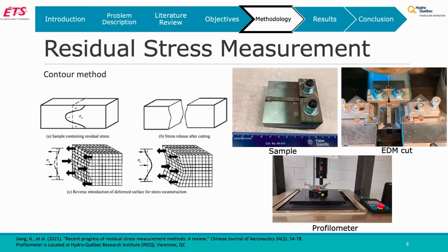And here you can see the sample, the CT sample mounted on the bolt head, and this is the EDM cut. So the EDM cut goes through the crack plane, the crack growth plane, and then I used a profilometer to capture that deformation.